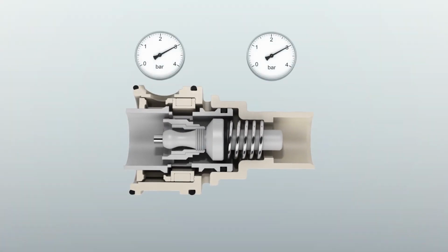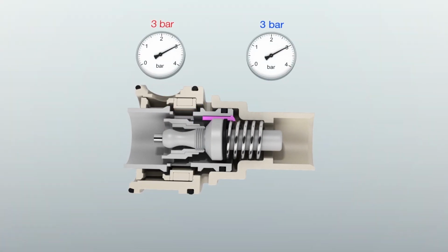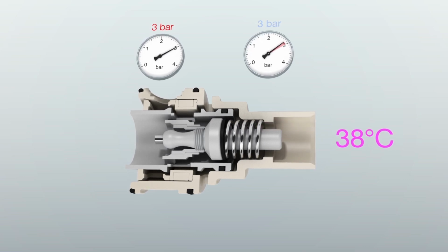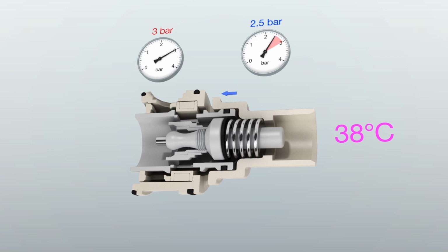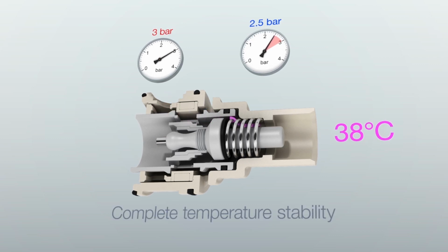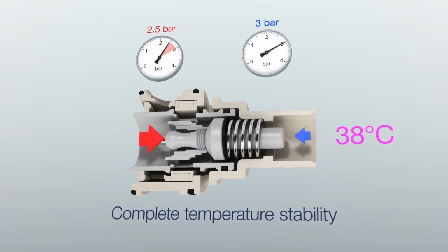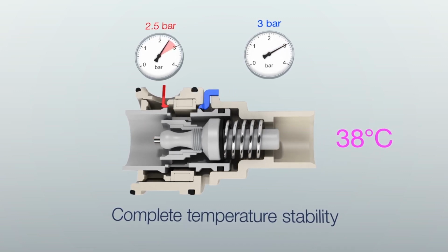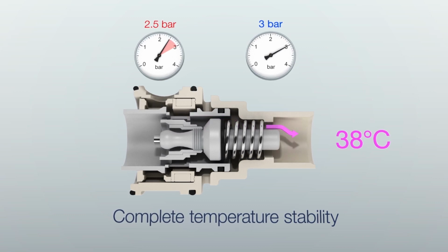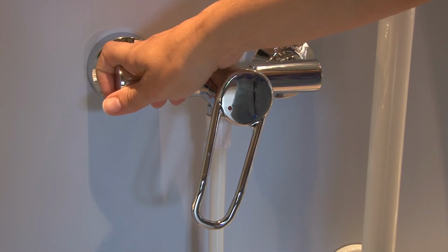The second technology is thermostatic technology, which, in the same way, compensates for the temperature variation in the system, and also pressure variations, especially if the cold water supply fails. The hot water shuts off completely, and vice versa, if the hot water supply fails, the cold water shuts off entirely. This avoids cold showers, but also prevents a loss of balance as a result of the temperature changes. An important detail is that Delabie's products feature also a SecuriTouch technology which improves safety and removes the risk of burn when touching the shower, since the mixer has thermal insulation.